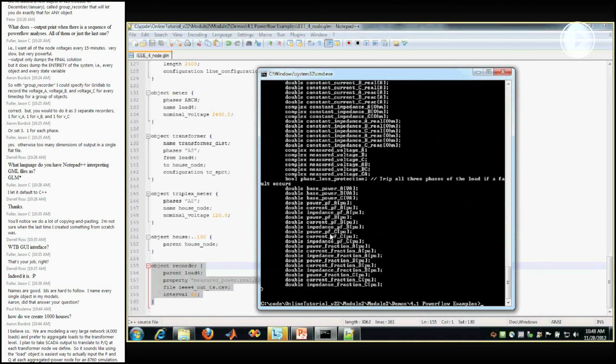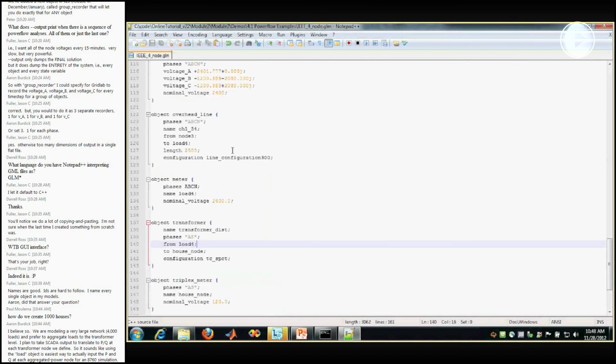So you can set the base power for each phase. That might be the SCADA output that you're looking at, or P and Q. And then you could set a power fraction for each of those components, so you can turn it into a ZIP model. So it would be a more direct way of specifying that, so you don't have to rely on just constant power loads or do any of the conversions that are necessary for different voltage levels. And you can mix and match those too.